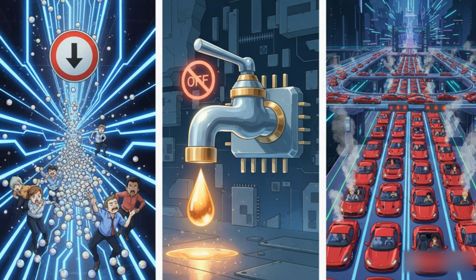Then in the middle, there's sub-threshold conduction. This means your off switch, well, it's never really off. It's like a leaky faucet constantly dripping current and just wasting power. And finally, the transistors get so mind-bogglingly fast that the wires connecting them, the interconnects, become the bottleneck. You've got these Ferraris for transistors, but they're all stuck in bumper-to-bumper city traffic. So yeah, we need some new tricks.